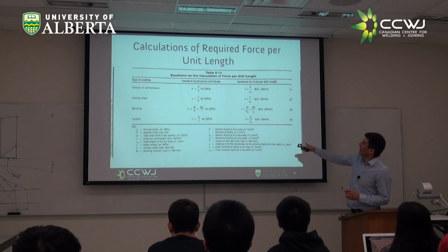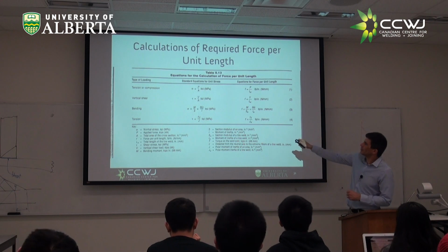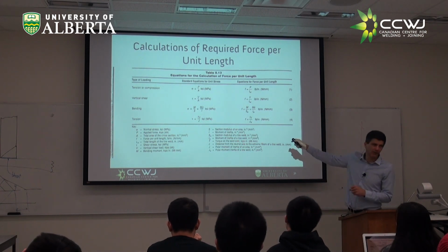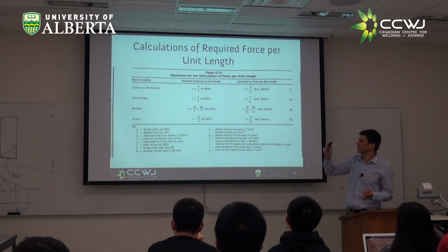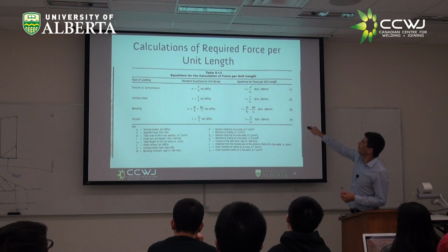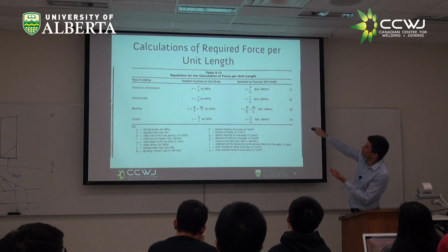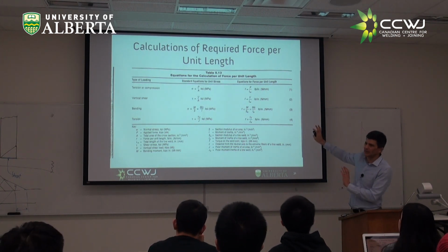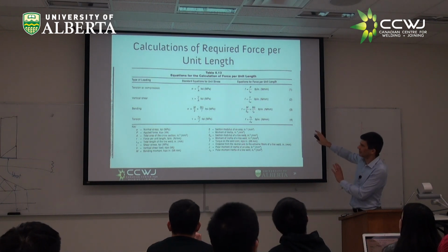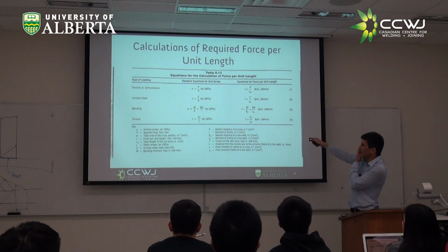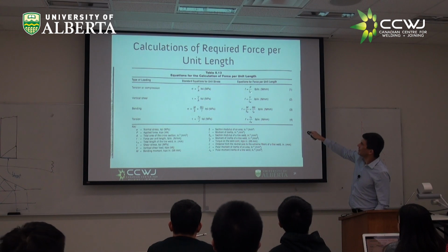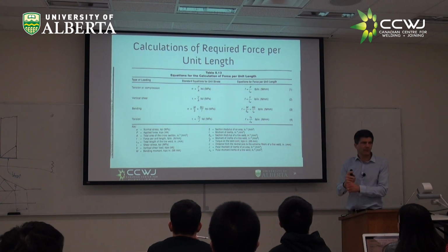Very easy. If it is a tensile test, you do force on area. And here you do force. You see, now they're using P for force instead of V, but this is from American literature, from the welding handbook. This is force divided by the length of the weld, for tension or compression.